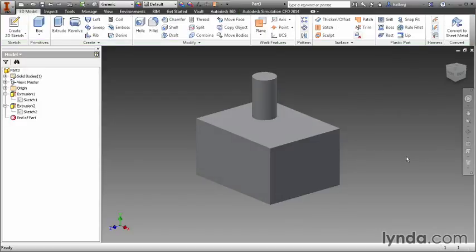Placed features, on the other hand, are different in the sense that they don't require sketches. They're actually placed on the model. So what is required for placed features is actually physical edges or physical components within the model. The most commonly used are fillet and chamfer, most likely. Potentially hole, but hole is a little bit different in the sense that it can be placed or sketched. It's very unique in that sense.